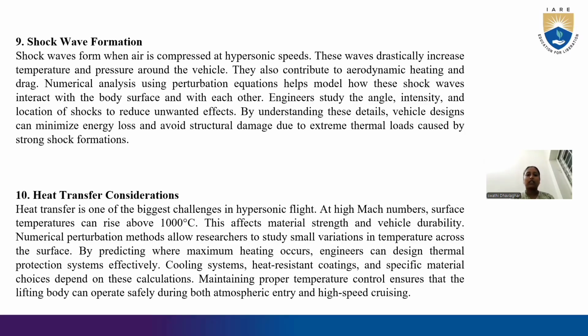These waves drastically increase temperature and pressure around a vehicle. They also contribute to aerodynamic heating and drag. Numerical analysis using perturbation equations helps model how these shock waves interact with the body surface and with each other. Engineers study the angle, intensity, and location of shocks to reduce unwanted effects.